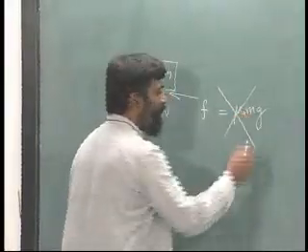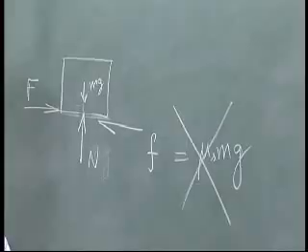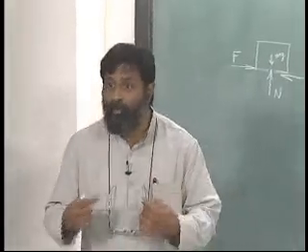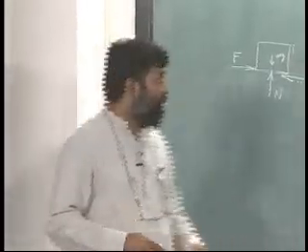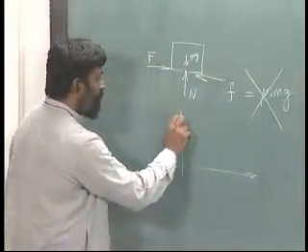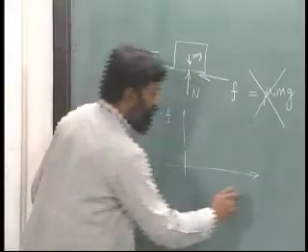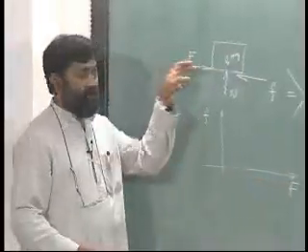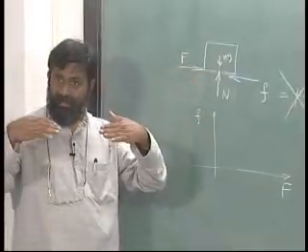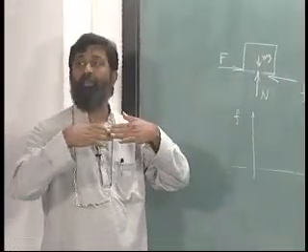Of course, in this particular case, when I say mu s is the coefficient of friction that I am talking about, static friction. This is true only when the body starts to move or is about to move. Okay. So, if I draw the frictional force F versus the actual force applied like this, mind you I am applying at the bottom so that it is easily understood that these two do not form a couple.